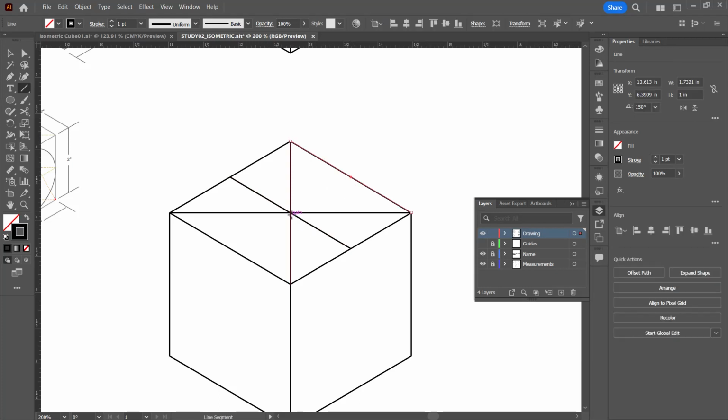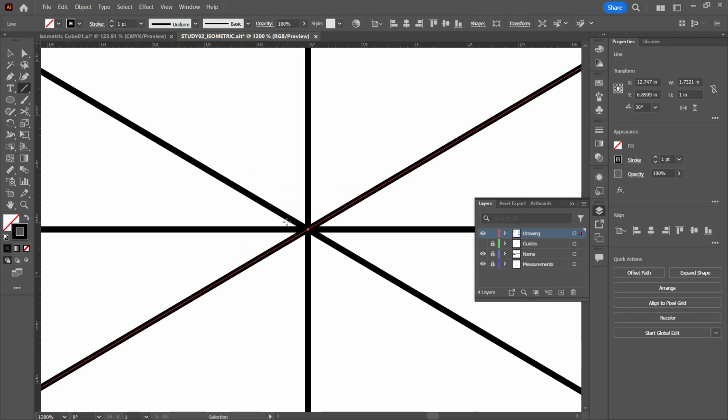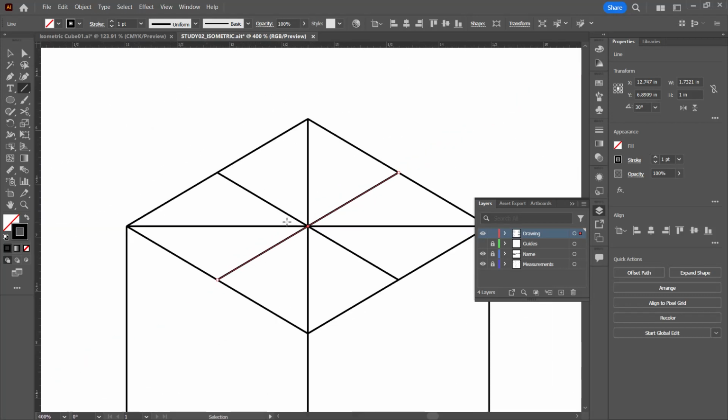Select this path, go to my center, start drawing. Hold Alt. I can see that's my center. And I've got it. Okay, so now I know those are all right on. If I zoom in, we should see a nice clean center point. It's easy, if you accidentally snap to other things, to be just a little off, and then your ellipse won't draw correctly. Okay, cool.